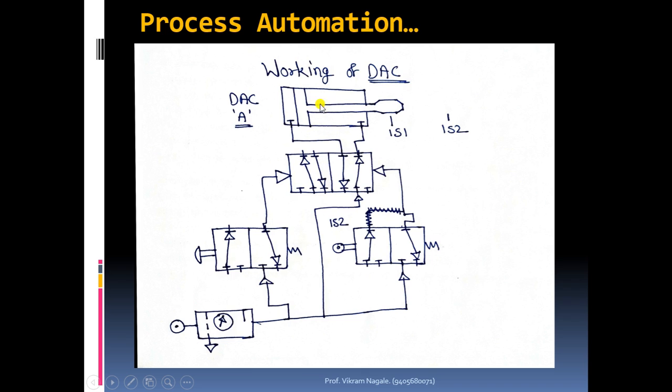Okay, so because of this there won't be any pressure on the right hand side of the piston, and there is a pressure on the left hand side of the piston, which is around 5 to 6 bar, and because of such a high pressure, that piston has to move to the right hand side. Rod end also has to come to 1:2 position from this 1:1 position, and while this extension is going on, if we release the push button, then what will happen?